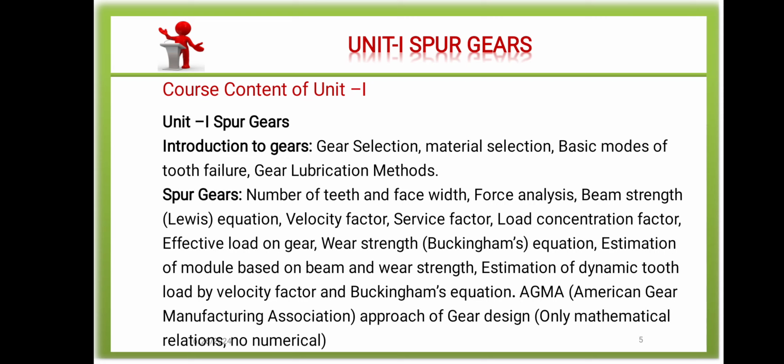Of course, the gear is the element which is in contact with another mating gear, and continuously there is material to material contact, and power is getting transmitted through this contact only, and because of this contact a tremendous amount of heat is continuously generated in that particular system. So there must be some system which can dissipate or extract the heat, and one of them is lubrication.